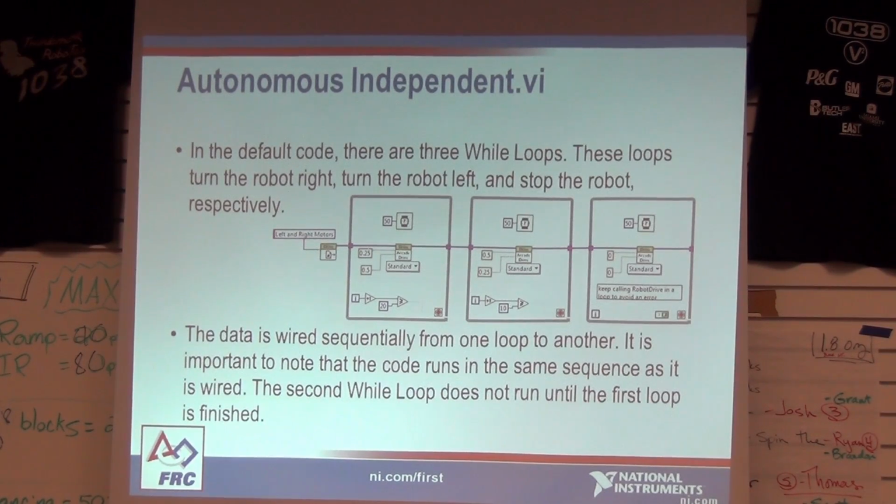By default, it gives you something like this. By default, this is in the VI, but it's disabled. There is a way to disable code in LabVIEW. If you go to your structures palette, you can drag a disable structure across like you do a case structure or a while loop. It will be disabled so that this does not automatically run if you forget that it's there. It's there, but it's disabled.